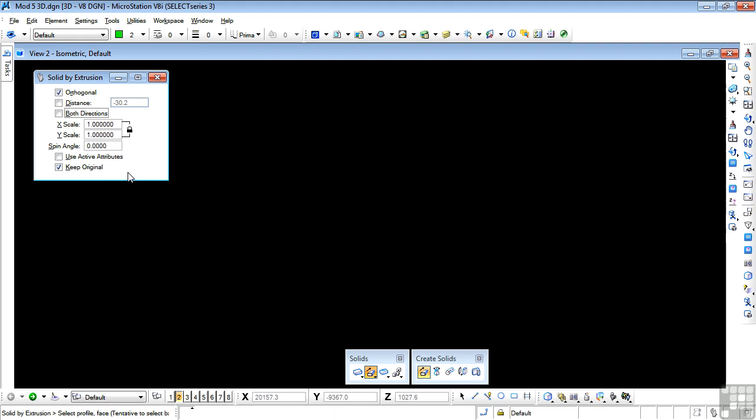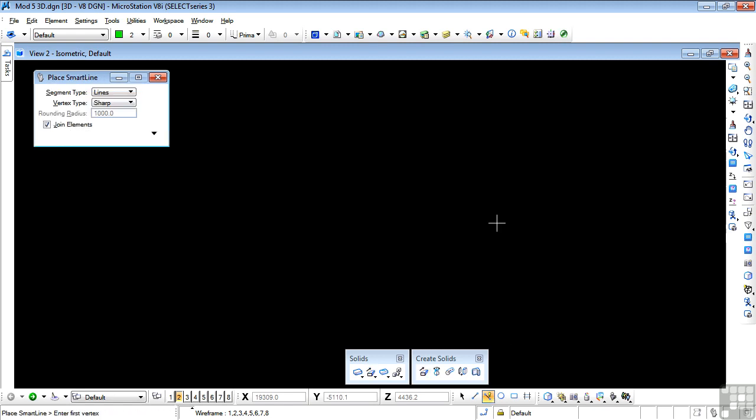You're going to need to switch between a wireframe view and a shaded view, and I assume that you've already set 2 function keys for this purpose. Let's start by looking at a simple angle. So make the settings that I have in here, except that I don't want to keep the original at this point. So only orthogonal is on. And we're going to draw with SmartLine. So start, I'm in the top compass orientation and no dimensions here for the moment. So I'm going to draw myself an L shape. Again, doesn't matter what dimensions I use. Hit enter and find that point and snap back.